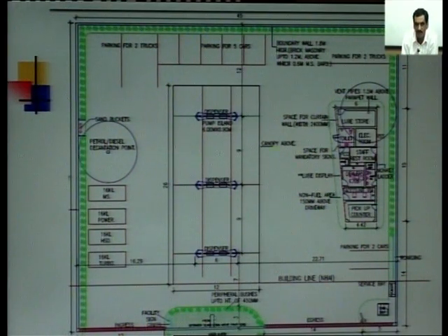Officially these outlets are called two-wheeler outlets, and officially larger vehicles, trucks or cars are not allowed as per their license. Practically they may be housing these kinds of vehicles, but again the minimum size of a petrol pump for a full-fledged outlet is 30 meters by 30 meters.